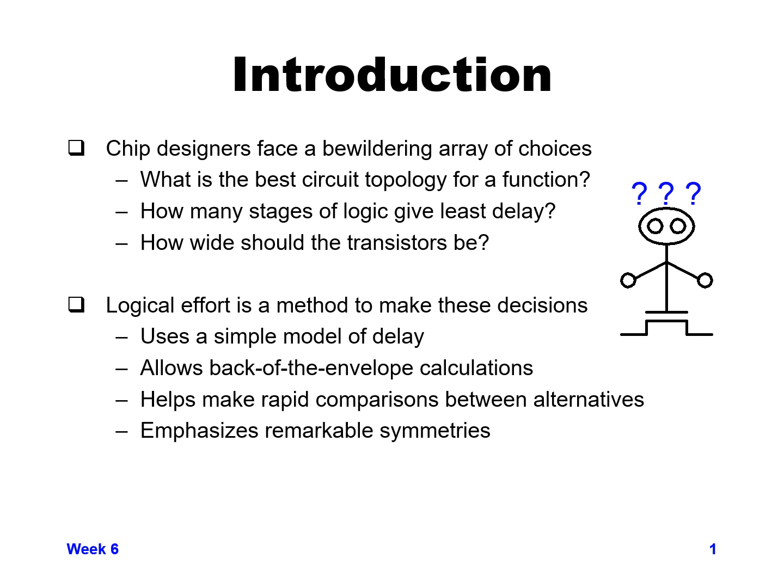So in the next section, I'll be going through a concept called logical effort. Logical effort is a methodology to help you make these decisions. It uses a relatively simple model of the delay on a stage-by-stage basis, and rather than going into very exact calculations for every single stage, it allows you to make simpler back of the envelope calculations that you can do somewhat quickly, but still be relatively close to reality in making comparisons between alternatives.